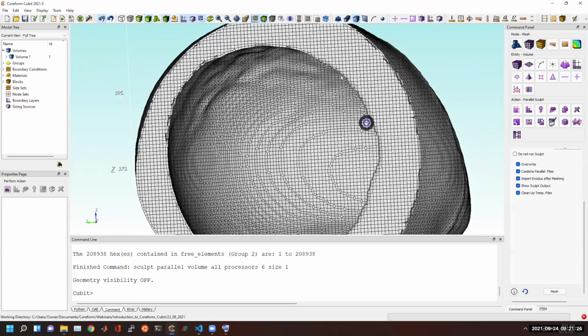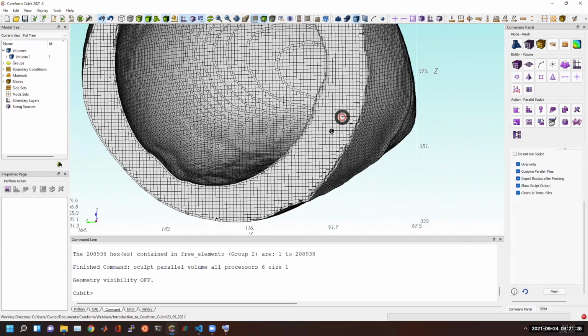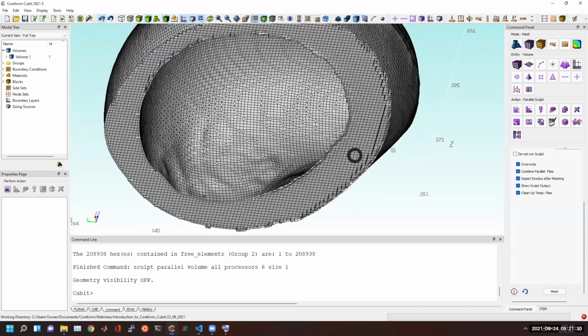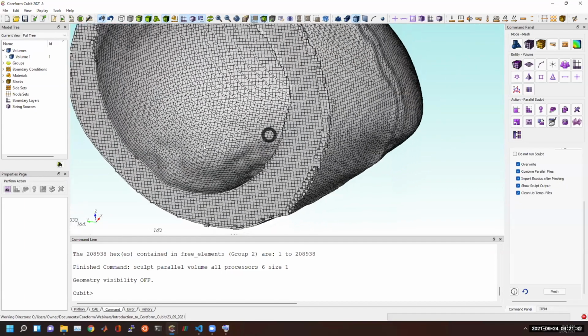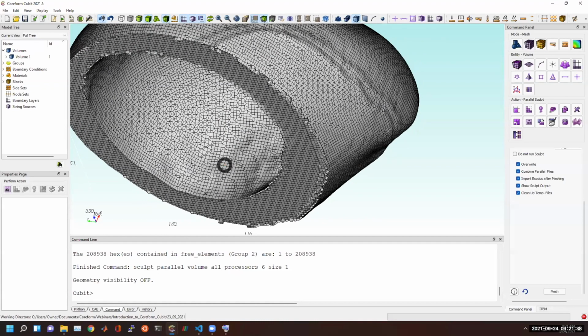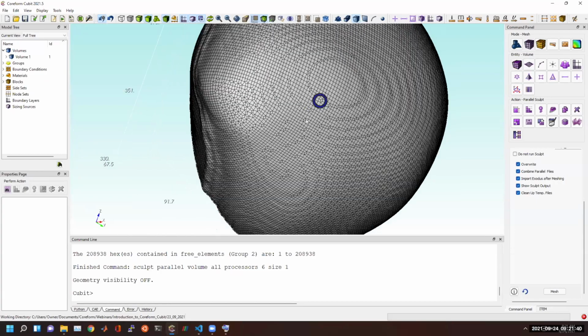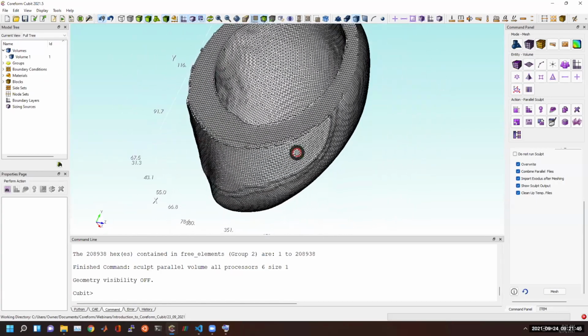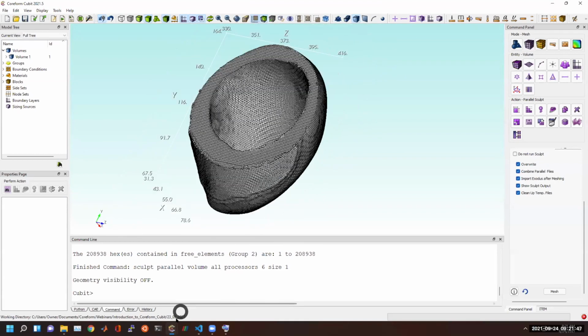But otherwise, you might expect these hexahedra to be more efficient than some of the tetrahedra. But it is possible that in thin regions, the tet mesher will capture those since it's starting with a known good triangulation, and the hex mesher may not capture those as well. But that's just another way to build a mesh of this heart.